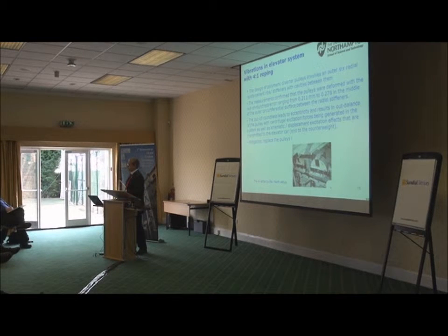Mitigation: replace the pulley. So there is an example where you have a very simple mitigation strategy. You do analysis, you find the reason, and you fix it. For example, replace the pulley. Sometimes it might be simpler. In a simple case, you can balance the pulley.